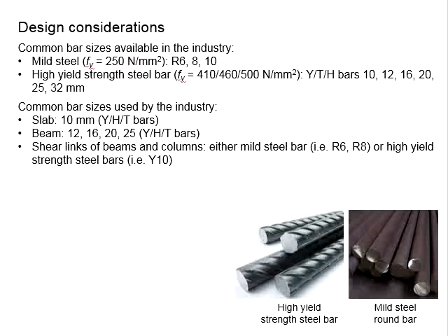In fact, you can have high yield steel bars larger than 32 mm. However, the problem is that they are heavy and difficult to work with. When the bar size is greater than 32 mm, first, it is difficult to bend. Although there are bar bending machines on site, you know that the reinforcement bar comes in a long piece, which is typically 12 meters, which cannot be handled by one person due to its weight.